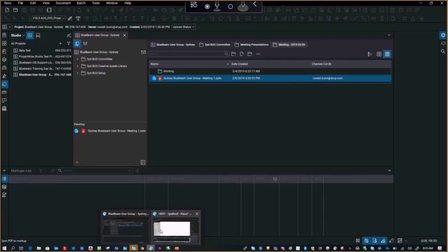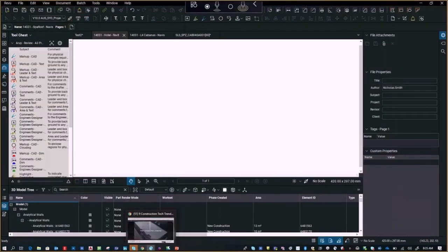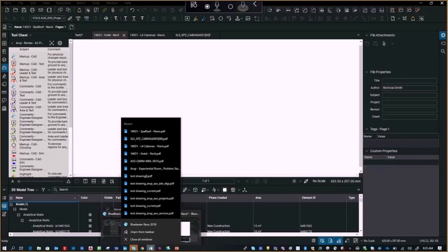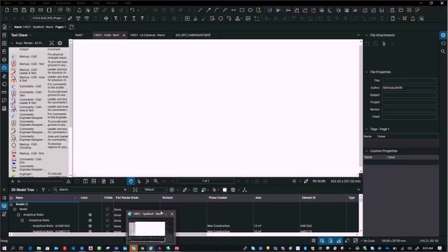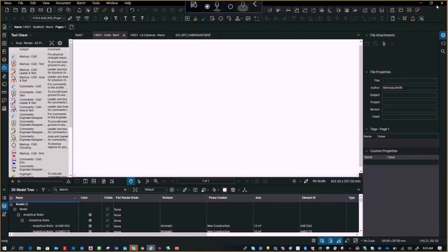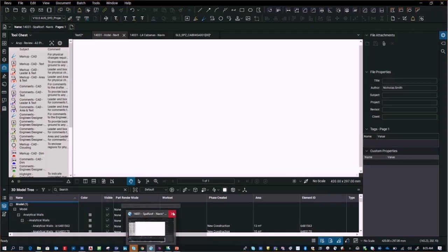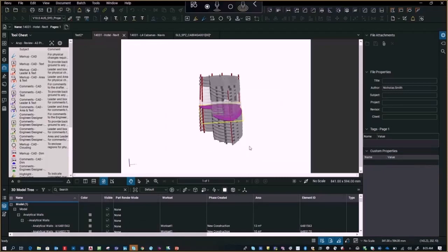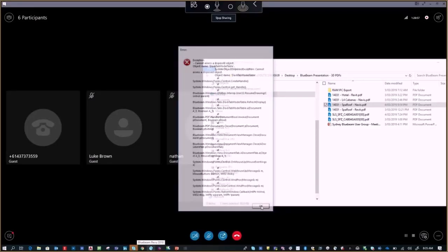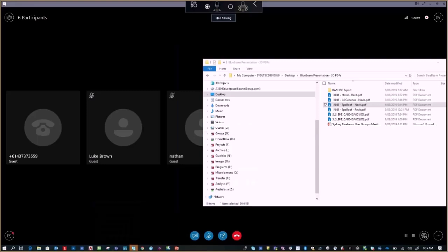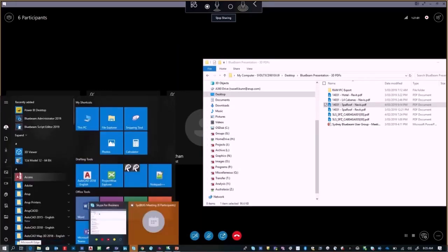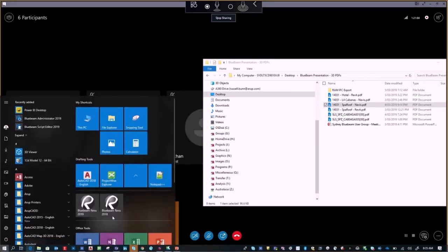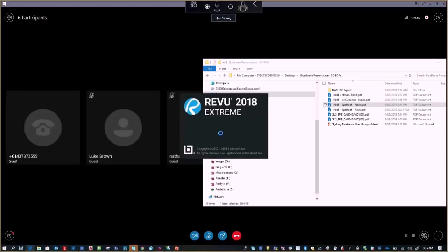Yeah, you could hyperlink it to that specific drawing, sheet or drawing set, whichever way you wanted. Anytime you want to figure out if you can do something in Bluebeam, just right click and you'll see all the options available. So there's no reason why you wouldn't be able to do that. You might just have to put a hyperlink on the sheet. Oh, I mean hyperlink the slab to the sheet. You can. Oh, you can? Yeah, you should be able to.